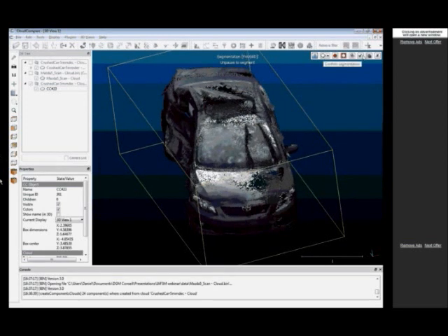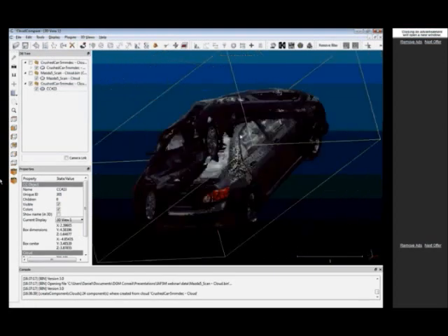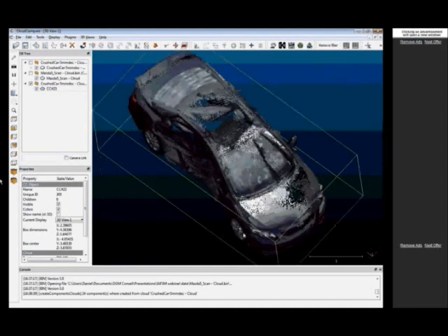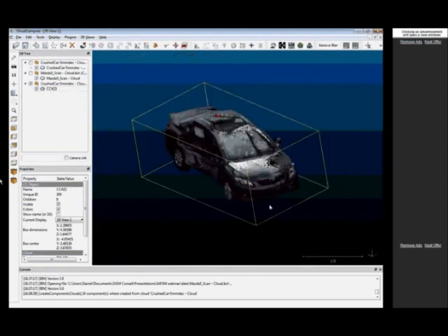And once you are done, you can confirm the segmentation with the green symbol, in which case CloudCompare will create two clouds, one with the points currently visible and one with the discarded points. You only keep the selected points. So let's say we have successfully cleaned both clouds to go faster.